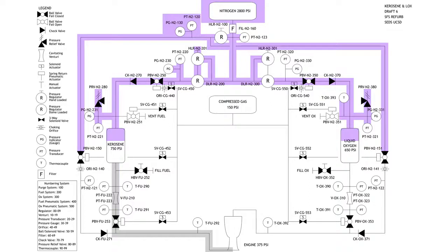Any questions about ball valves, check valves, pressure relief valves, gauges, thermocouples, pressure transducers? Can you explain thermocouple again? Yeah, so thermocouple, do you take ME 170 eventually? No? I think Aaron had a good way of explaining it. Aaron, you want to explain it? Yeah, so from my understanding, remembering what they talked about in 170, you have two pieces of metal that are close together at the tip that are made of different metals. Like one's going to be copper, one's going to be something else. And because they're different materials, they have different properties, and you're going to get a potential across the two metals just from having a temperature.